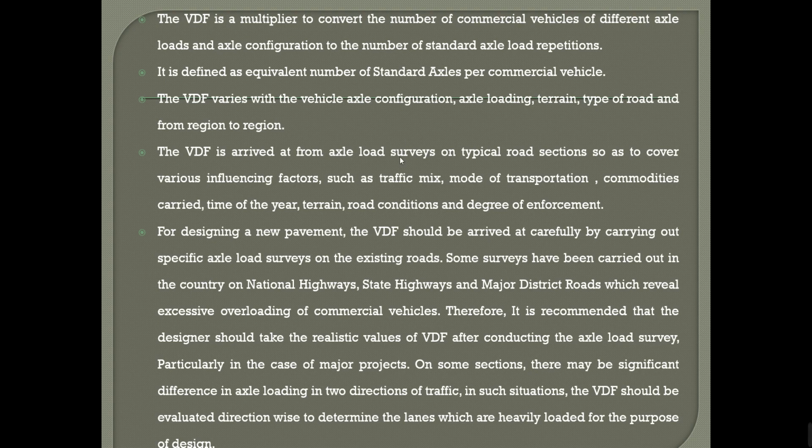For designing a new pavement, the VDF should be arrived at carefully by carrying out specific axle load surveys. As we discussed in the last class, based on the axle load survey, we will be able to note down the amount of axle load that a particular vehicle carries, and the different axle configurations it possesses.